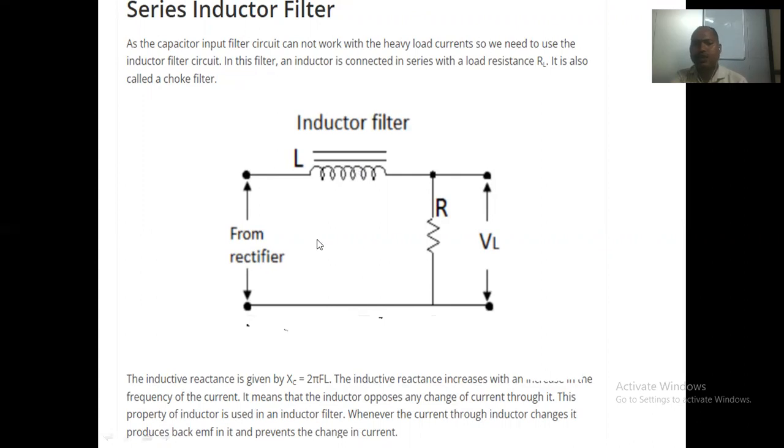So what it indicates is that it gives zero reactance for DC, right? When we apply an AC signal, in that case it gives the highest value. Highest value indicates that no AC signal should pass through it. So for that purpose, the device used across here should pass only the DC signal, but it is not an ideal device, so it contains some remaining ripple. That is the thing with respect to the inductor type of filter.